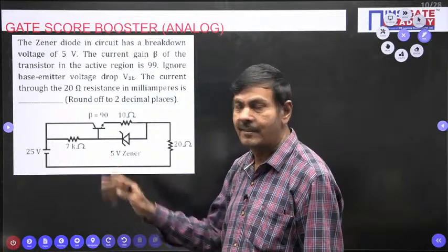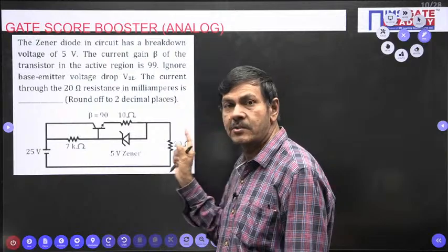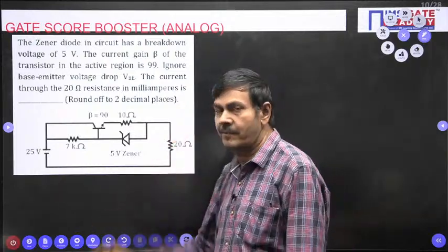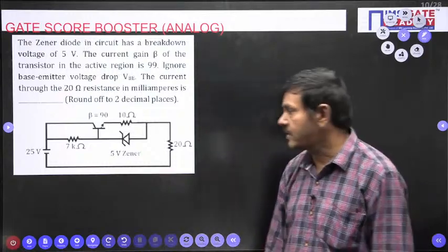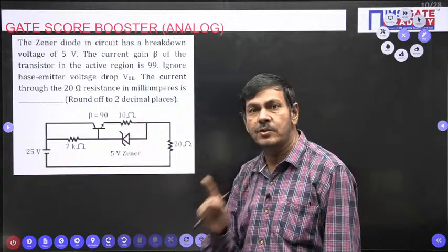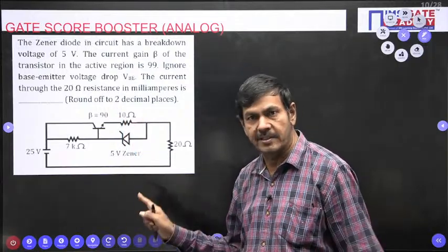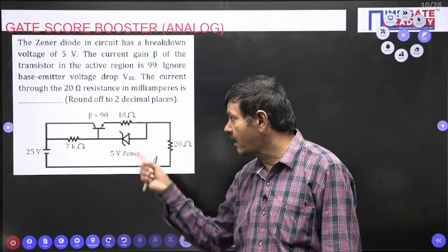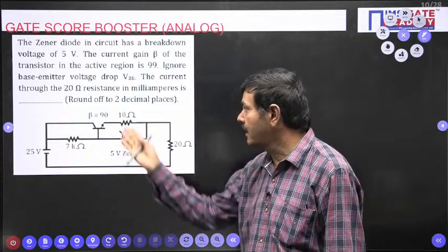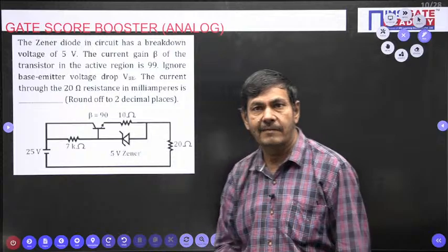If you got less than 5 voltage, Zener is in off state, and our assumption is correct. So when a Zener is connected parallel to a resistor, assume at first Zener is in off state. The current across 10 ohm and 20 ohm will be the same. I will do here, you please watch.